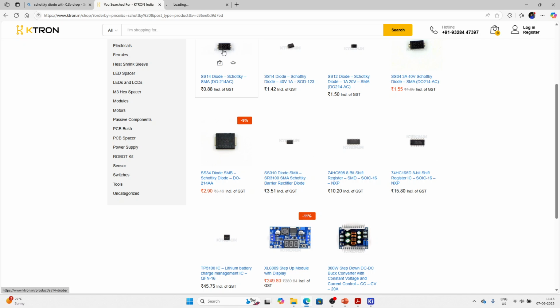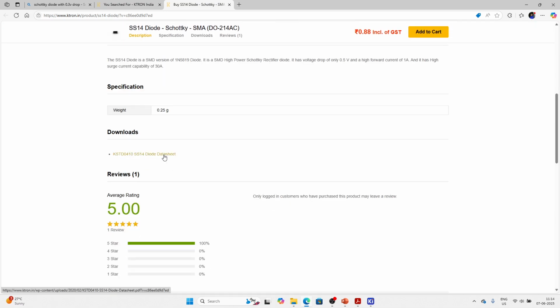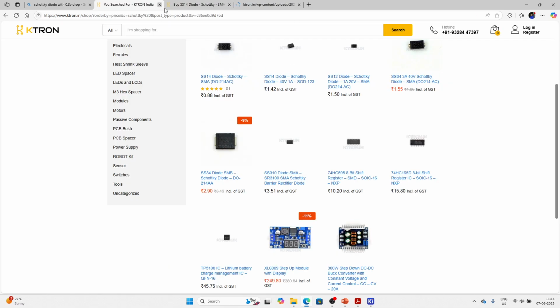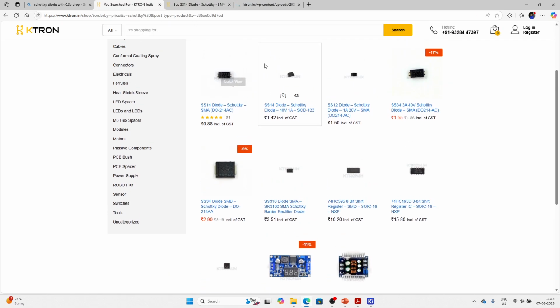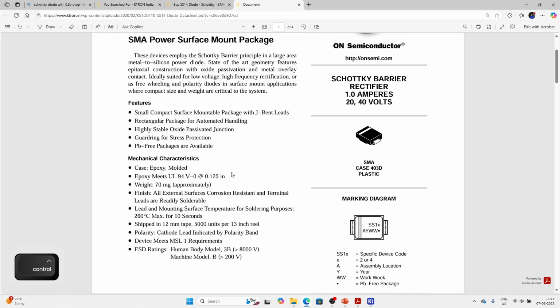So this might be the one. Again, we might have to change the symbol for that. It might not be 0603. Here peak current is 1 amp, blocking voltage is 40. I need to check what the dropout voltage is for that. Or we can go with 40 volts, 1 amp. Again, this and that might look very similar. Let's see what the dropout is.